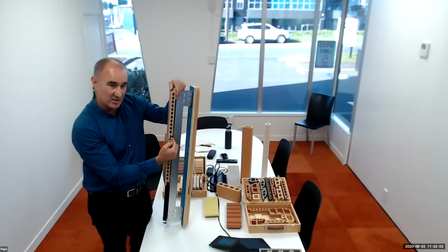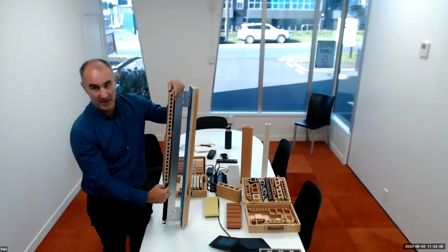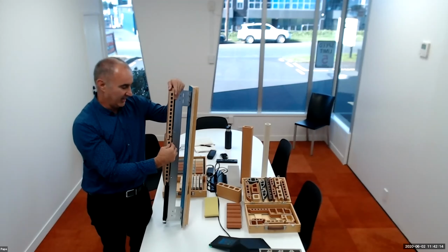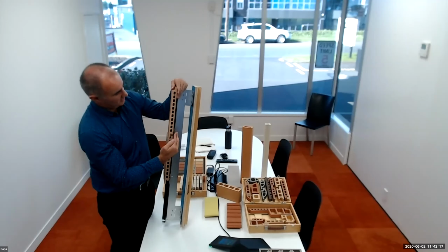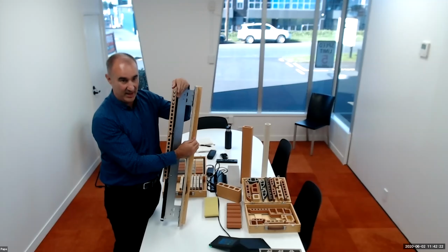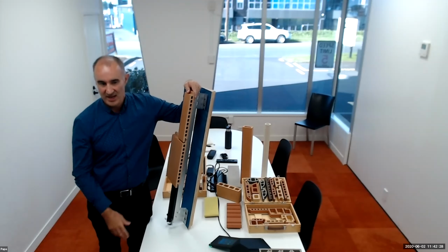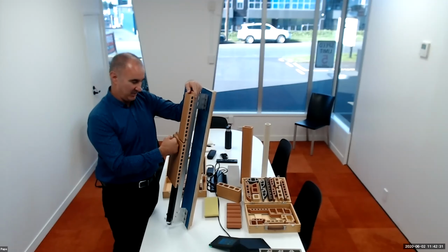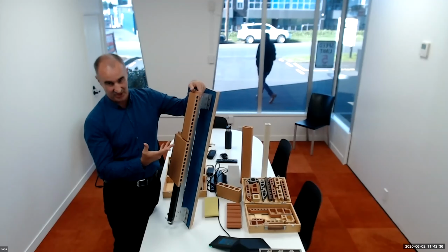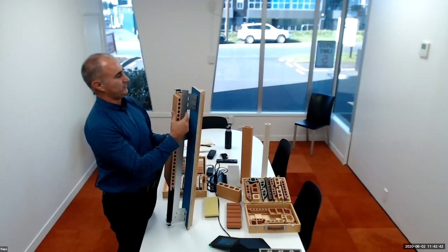So when it gets in behind the tile here, it's under no pressure. So all it's going to do is either just drop straight down the back of the tile, or because there's constant airflow in this area here, ventilating it out, it's just going to evaporate out. So the idea is that no water is getting back to your weather-tight layer. It's protecting that layer. So it's obviously going to be far more watertight for a heck of a lot longer because the elements are being stopped at this point here. Nothing's getting past the terracotta. Well, sorry, a little bit is, but nowhere near as much as what you would normally associate with it.